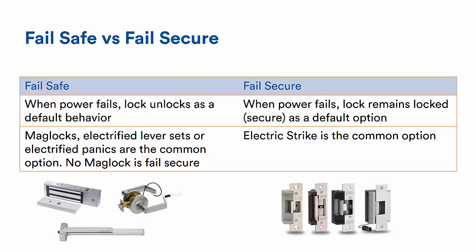Now, in the UK specifically, and a number of other European countries, you cannot use maglocks on emergency exit path doors, as these need a mechanical means to override the door without creating a potential spark, especially if there is a gas leak situation. Since maglocks secure an opening with electric current, a spark can occur. So again, any door secured by a maglock is also an emergency exit door that must be retrofitted.